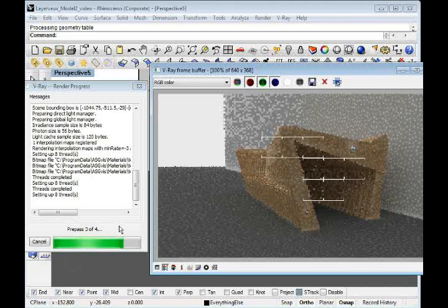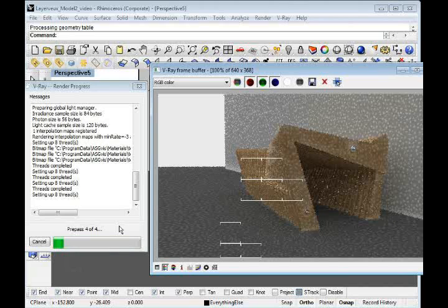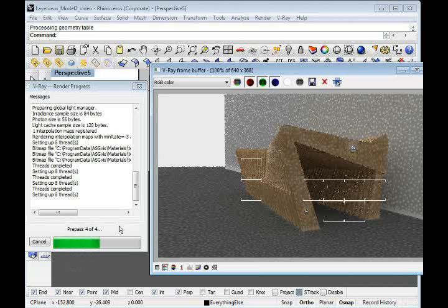Glass is the most difficult thing to render, and I recommend rendering glass at, say, the most minimum basic, with a slight reflection to it. Keep it to a minimum because you can always bring it into Photoshop and enhance it with the real glass. So that'll make your model look that much better. Already we are in the 4:4 pre-pass, which is really good. Then again, there's not much here except for a series of ribs connected to its back legs. So I guess we'll wait until it's finished rendering.